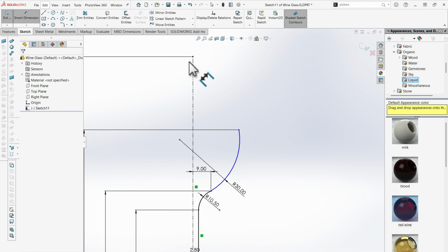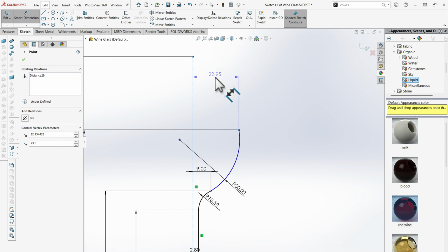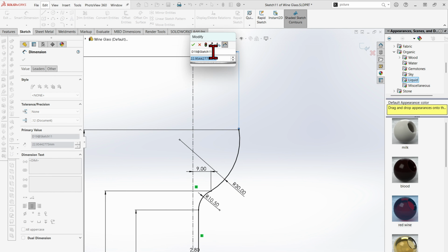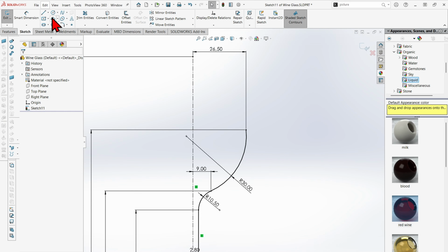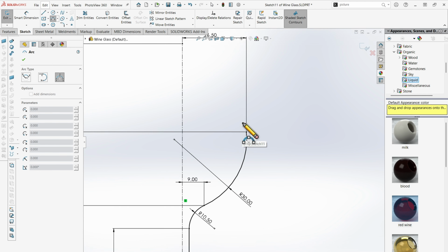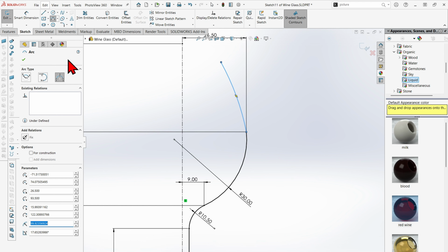And then from the center line to that point, I make that to be 36.5 millimeters. So we're just gonna come there, select our 3-point arc, and then click at the point, drag upwards, far left, and then click anywhere, drag it down, and control the radius, just dump it there, around 99.